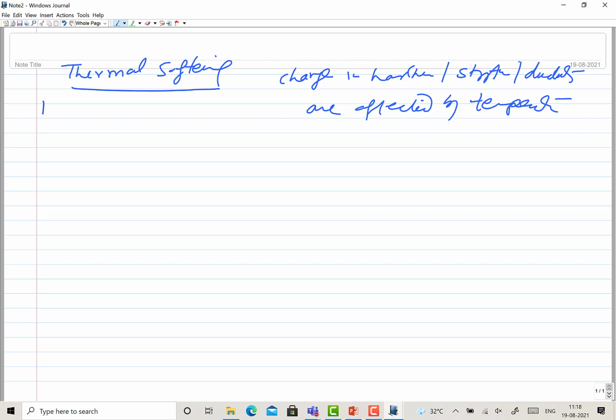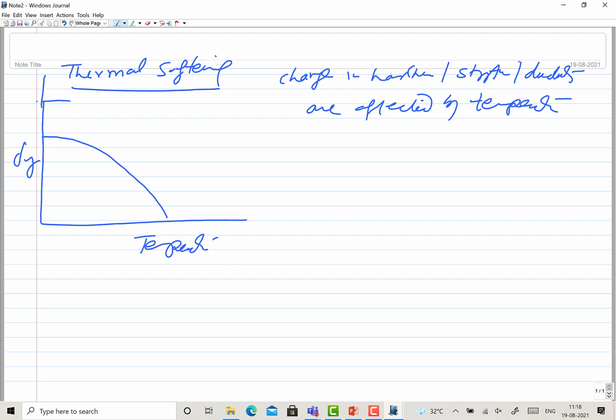Sub-zero temperature behaviors are completely different from what we get at a higher temperature. One simplest example: most metals in general, if you take aluminium, will show a tendency like this with the increase of temperature in terms of, say, sigma y. Mild steel at room temperature is of higher strength, but it may come down very rapidly, so this may be 100, this may be, say, 300. Taking further higher temperature metals, maybe around 400 to 500 degrees centigrade, say, for austenitic stainless steel.